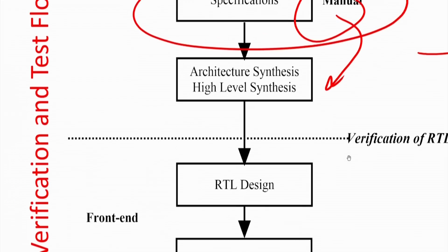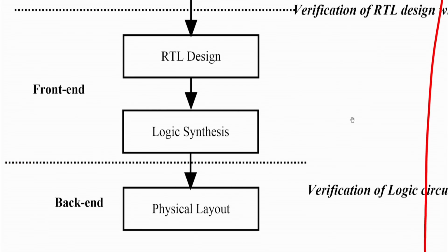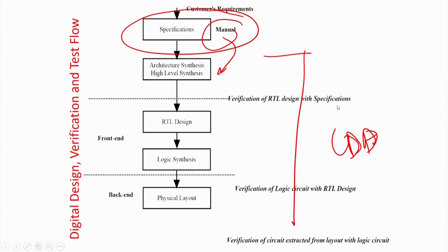This is a full-fledged CAD flow, because of course we know that a Karnaugh map can generally solve up to 5 variables, Quine-McCluskey can extend it to some more variables, but in the case of circuits there will be more than 1000 variables, or even much larger than that. Then there are optimized tools, an algorithm called Espresso, which is a heuristic that solves this in a much faster manner. Let me now come to an example of optimization.